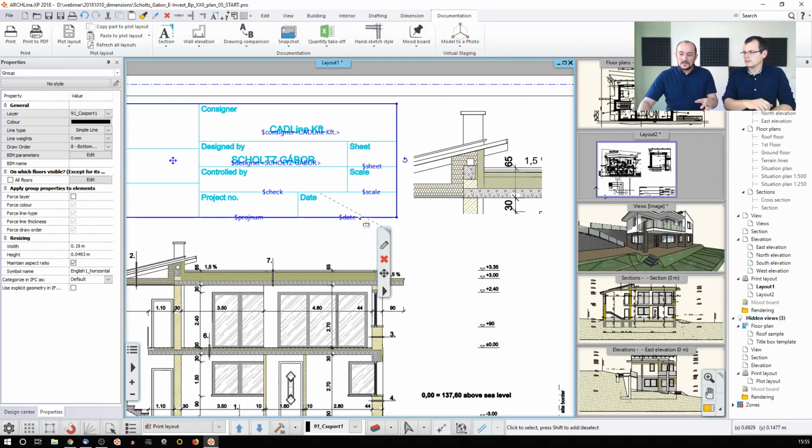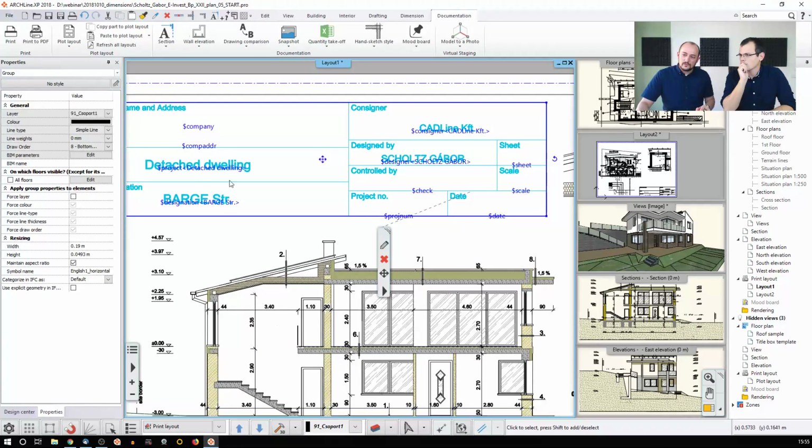That's a variable. You can actually use them when you create a plot stamp: you type a text $date and you paste it somewhere, then the software will auto recognize it when you enclose it into a group and use it as a plot stamp or title box, and it will automatically use it the same way. So this way you can actually peek into what sort of variables you can use if you want. You don't have to. Most of the time, I simply fill up a plot stamp or a title box by myself as I would ever fill fully, and then I just change that. That is also something that works fine.